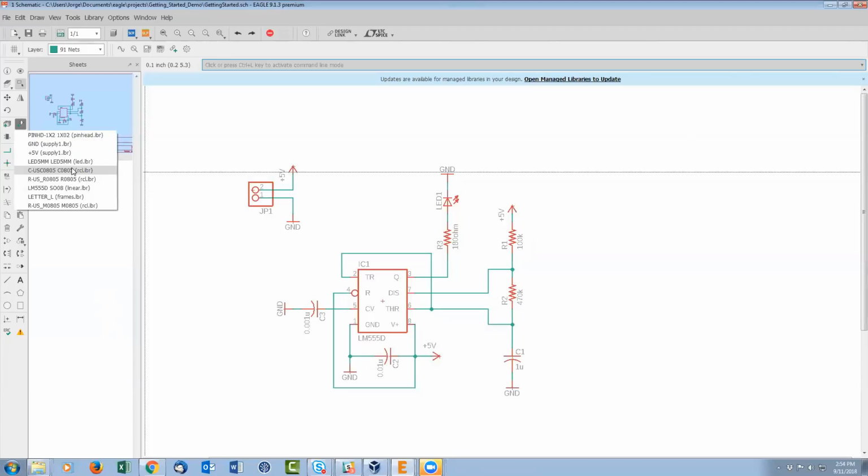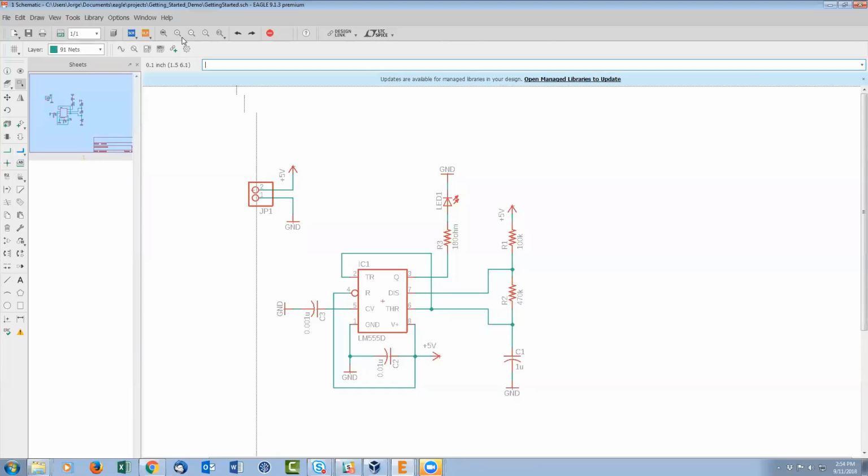Now, the components after they're placed on the schematic, no longer on the board, no longer depend on the library. But if everything is kept pretty organized, they will continue to back reference the library. So if you needed to edit the component or access the component from the schematic to the library, you should be able to right click it and select the edit option.